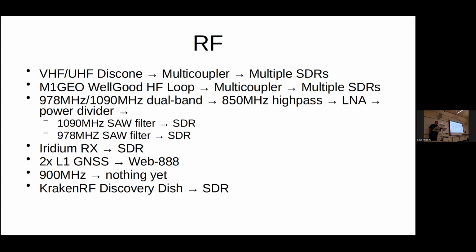Where do you implement the high-pass filter? I built it. It's an LC filter, and I used the SVC filter calculator, the standard value component filter calculator. Most filter calcs will tell you to use an inductor of 1.03857 nanohenries, and I can't find that on DigiKey.